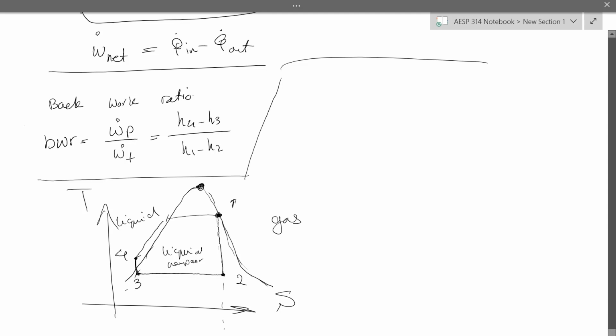So this is the case at station 1. Just after the boiler, we have boiled it up to saturation condition, saturated vapor. Then we send it into the turbine. It loses some of its energy, which means you're going to have some expansion. Temperature will drop. See this process? Temperature is dropping, and also some of your vapor, this 100% vapor, is changing its phase to liquid.